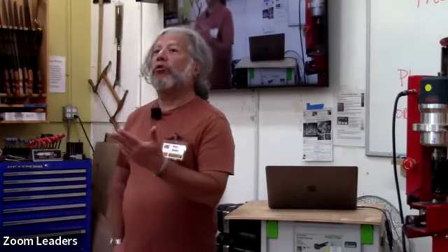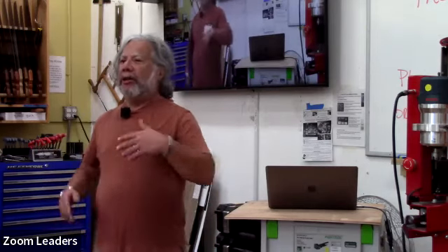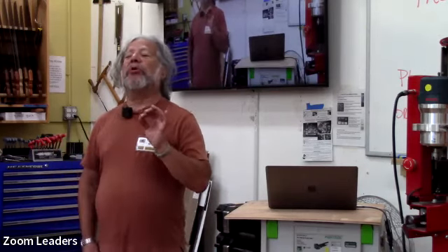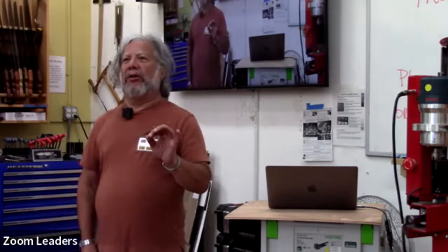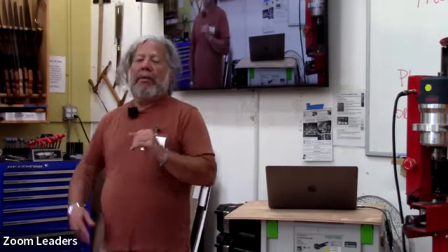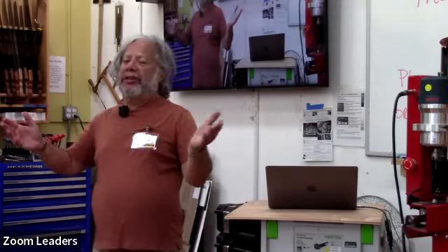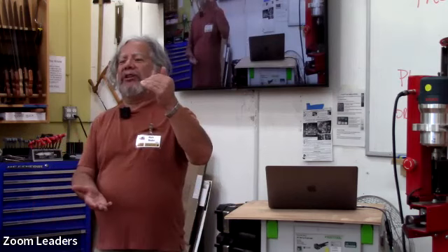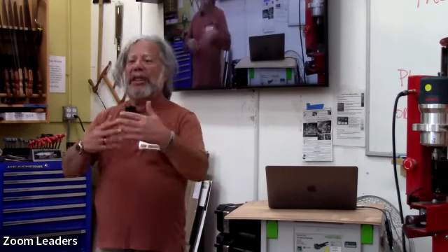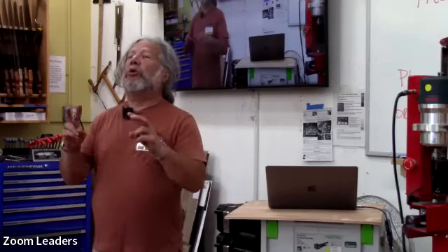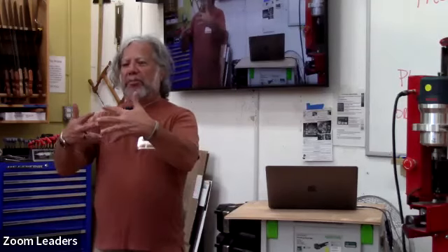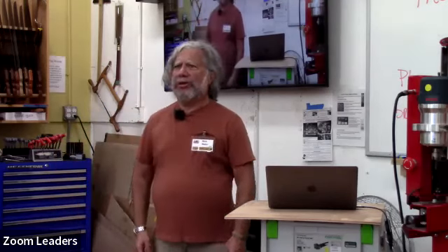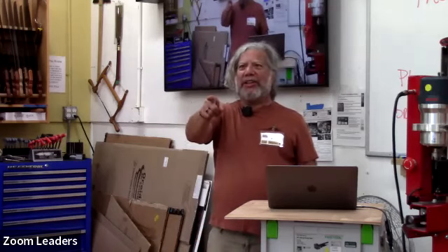You had to write some code to convert your... The question is, did I have to write some code in order to do it? No, I didn't have to write code. I needed to enter some parameters in the machine control software to tell it about my machine. And one obvious thing is, how big is your machine? I had to tell it, okay, it's 2 by 2. What's your Z-axis clearance? Oh, I had to tell it that also. So that was some of the parameterization that I needed to provide to make the control software sync up with my hardware. Good questions. Mark, you're paying attention.